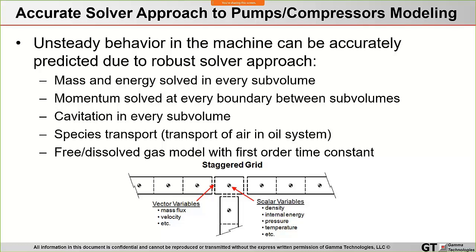And so that's the same governing equations you would solve with full 3D CFD, just reduced down to one bulk flow dimension along the axis of a one-dimensional pipe. And so by solving the Navier-Stokes equations, that includes solving for conservation of mass, momentum, and energy, but also conservation of species as well. And that allows for things like species transport.